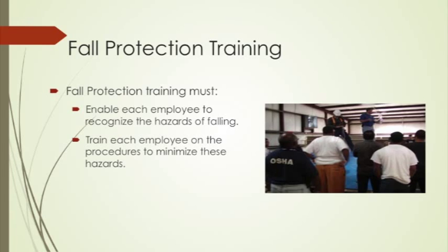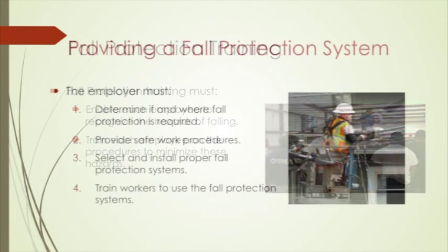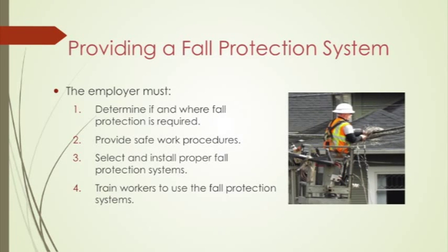The establishment of a proper fall protection system is critical to providing employee safety. The evaluation and planning should occur before employees set foot on the job site to perform work. It is the responsibility of the employer to perform an assessment of the hazards and provide a plan for protecting workers from falls. Some situations may require an engineer to design anchor points and deal with other considerations. Once fall protection systems have been installed, all workers must be trained and know how to use the fall protection equipment that is in place.